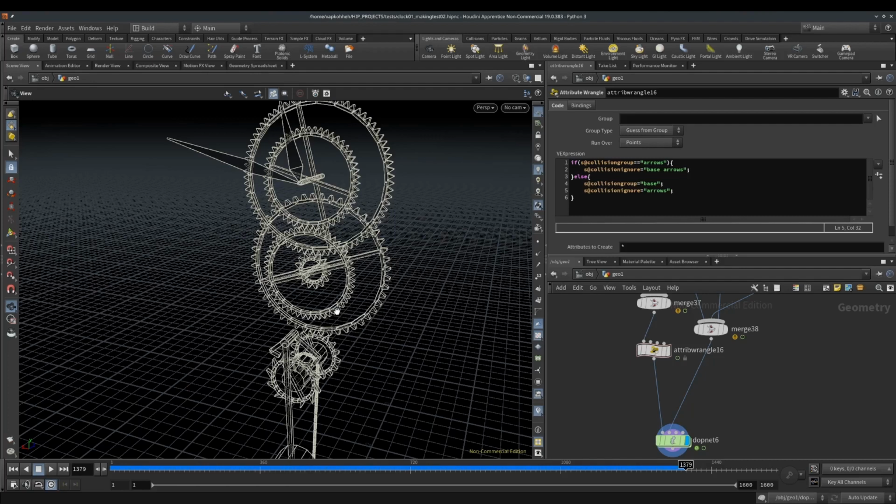I wanted to ask if you have had success with the impacts data, because something that we haven't really been successful in doing is that impacts data is giving you a bunch of things, but it doesn't give you the name of the packed object which collides. It actually does. It gives you the name of the object that collides, and then it also gives you the primitive number of the collision. It doesn't give you the primitive number inside the detail, if you're talking about that, so you know which bullet objects collided, but you don't know which exact primitives. But you can kind of estimate it knowing what the ID of the primitive is.